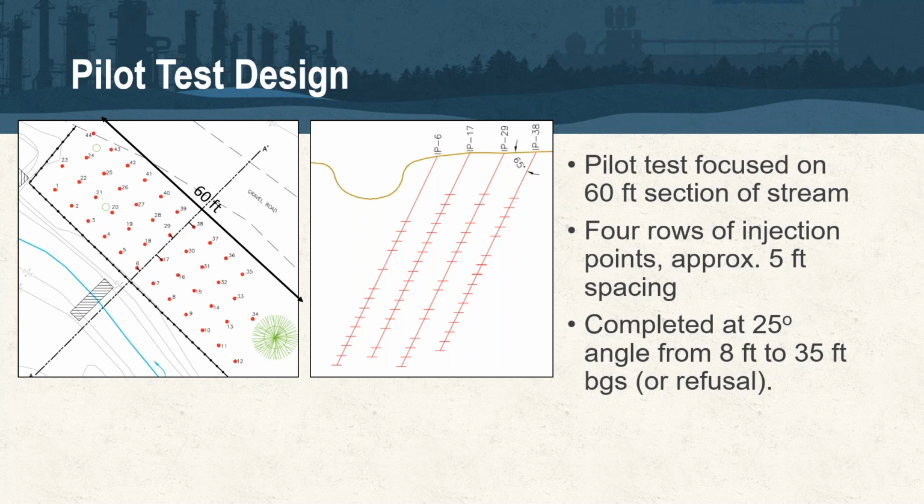And so those are injected at relatively high flow rates. The pumps we use are positive displacement, so it's whatever pressure is needed to meet that flow rate. And so pressures are obviously going to vary quite a bit. The injection systems that AST uses on most sites max out at 1200 PSI. That's system pressure, not downhole pressure. Downhole pressures in general are going to vary, say, between 50 and 500 PSI, I would say, for most sites, once you peel out the system losses. Other sites, bedrock and things like that, pressures can be a little bit higher.